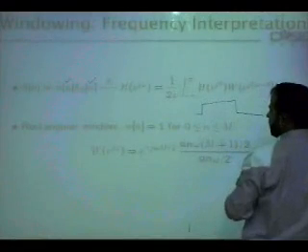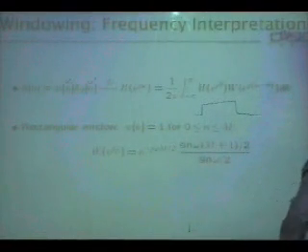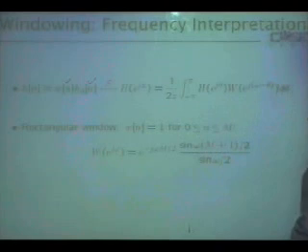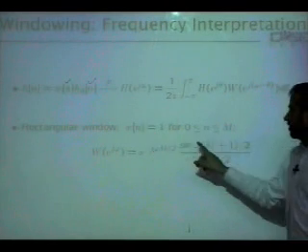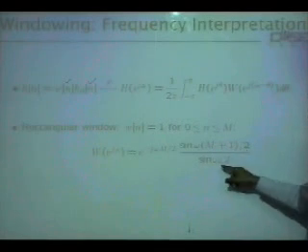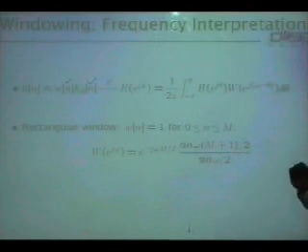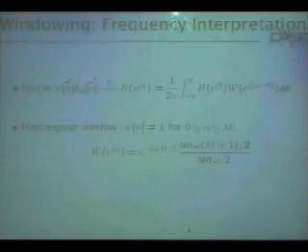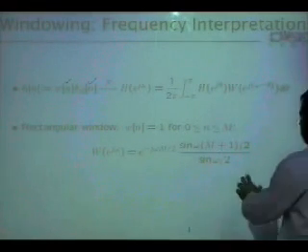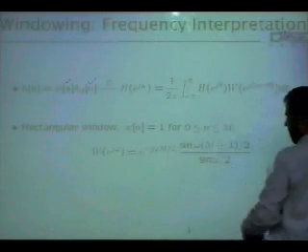This window's response is a sinc. Okay, it is a sine. So the frequency response of this is a sinc, sine of omega (M plus 1) over 2 divided by sine of omega over 2, and this includes the shift because it's shifted, but at this point our focus is really to learn more about the sinc, the magnitude.